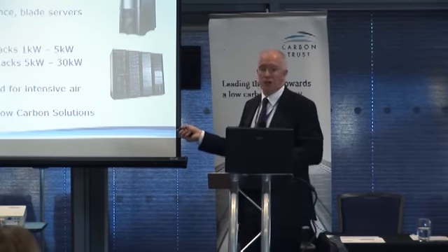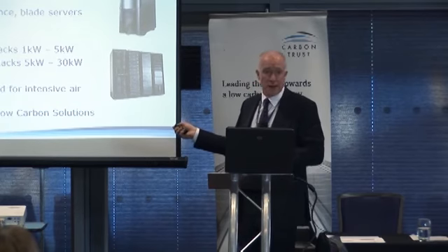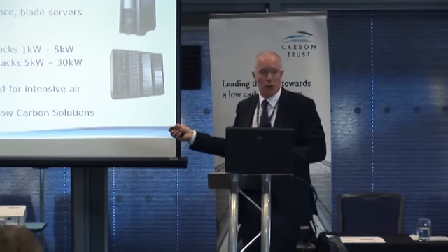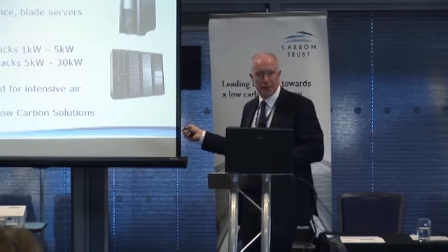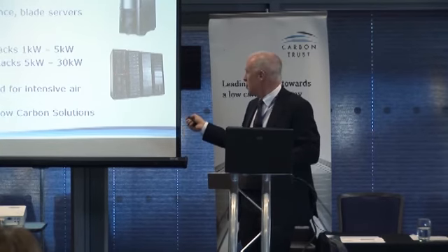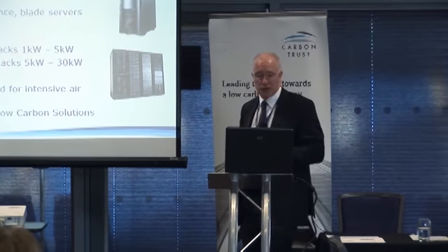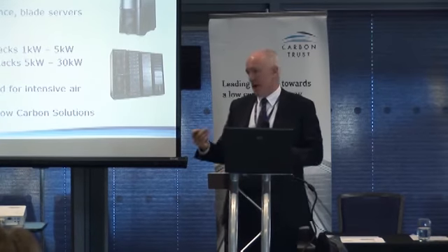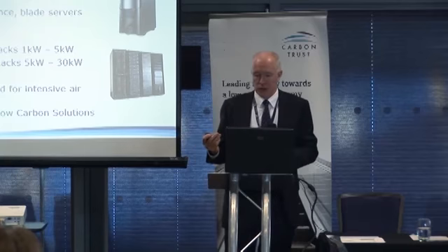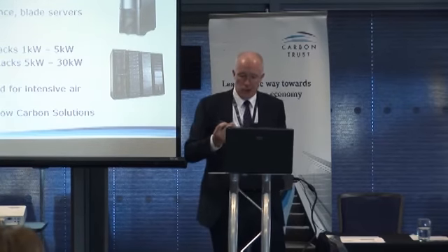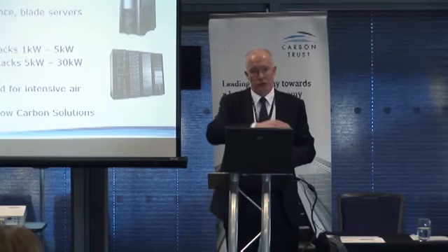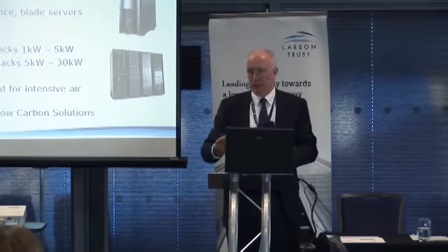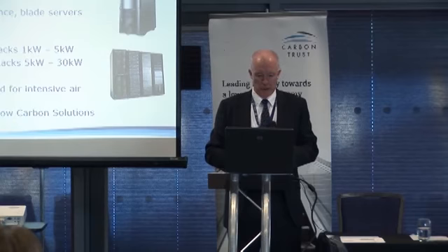And if you can keep the wattage per rack low density, then you can often do a lot more free cooling. If you've got very high density racks generating a lot of heat, perhaps for research computers, a large number of servers racked up here, then you're going to have to move to active refrigeration. So again, it's really important to look at how many pieces of kit and what the rating of those bits of kit is per rack. If you spread it out more, you're likely to be able to do a lot more free cooling.